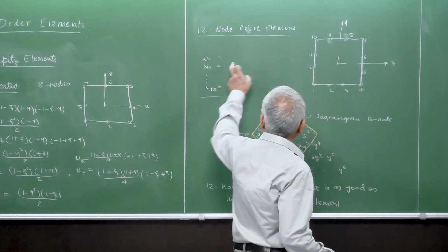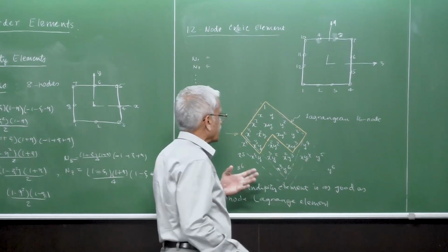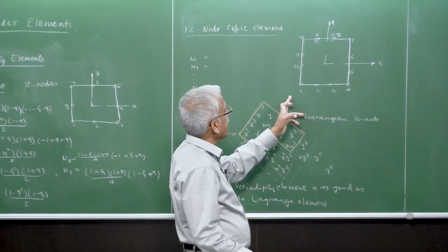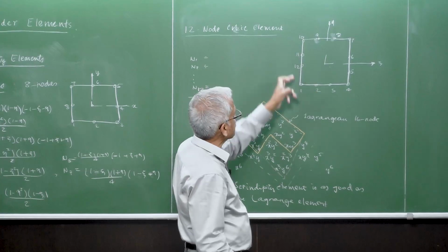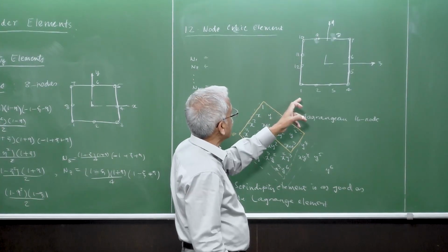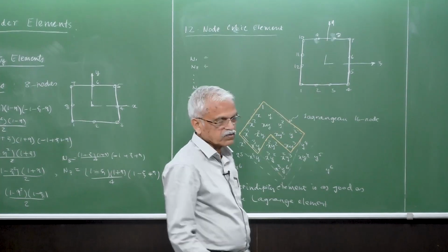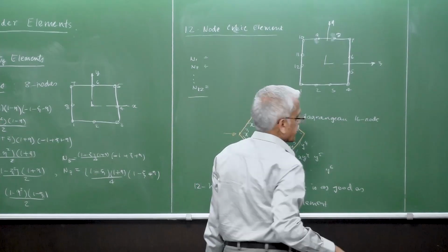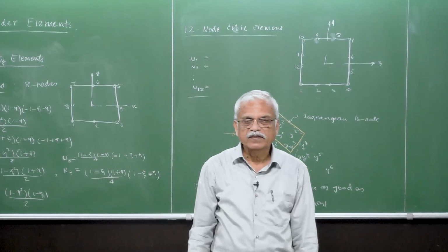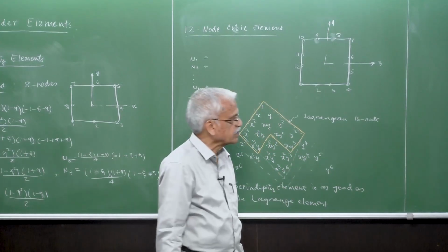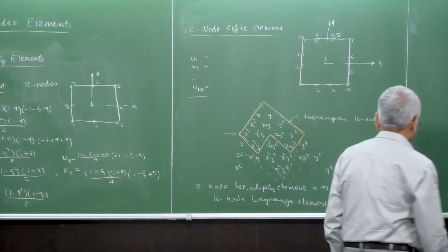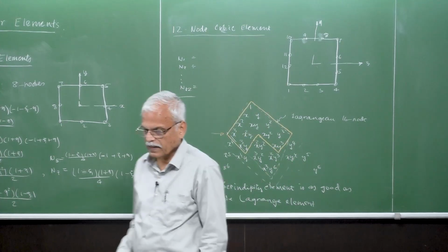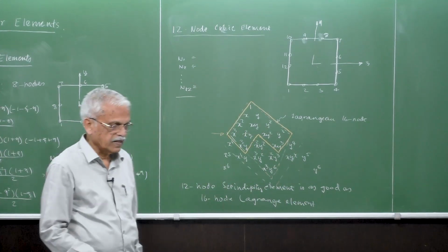There is a method in that sense, that there are Lagrangian polynomials on this side and linear on this side, constructed like this, and that's for the non-corner nodes. And for corner nodes, you have only the bilinear, on which the manipulations are done. So you can just look into any textbook for this. Okay, so this is how we construct the serendipity elements.